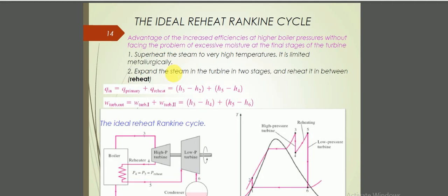So what can we do? How to increase the efficiency? Mainly what we can do is we can go as high as we can, increasing the temperatures as high as our materials can withstand. Then we can do one more thing, that is reheat. It is one of the most important points, that is reheating.